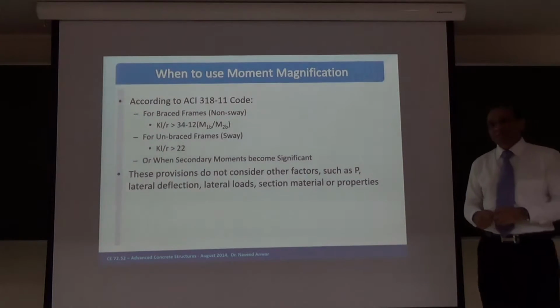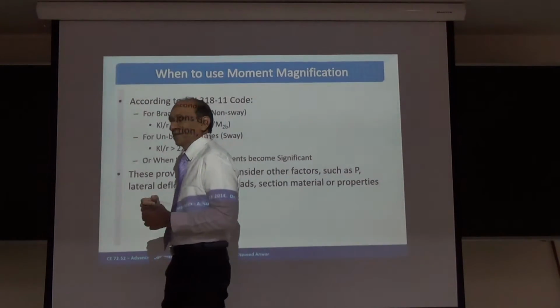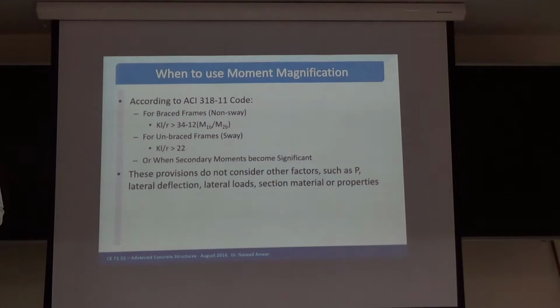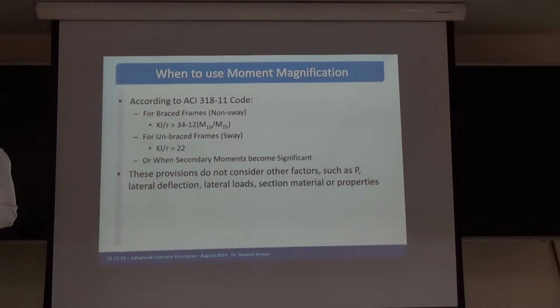Another issue is that Mr. Ong might have told you that one of the important factors is that the columns must be stronger than the beam, right? But in a small building, it's impossible to do that because of the span. Let's say it's a tall building, 7 meter span. In that case, the column will be 1 meter by 1 meter, the beam may be 0.7 or 0.8, so the column will be stronger than the beam in any case.